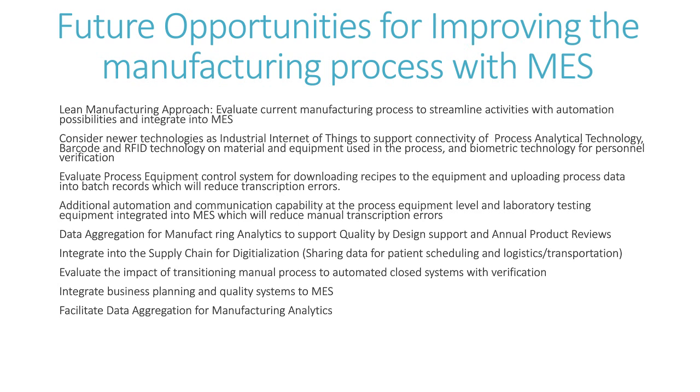You could look at the process equipment control systems and look at how we can download recipes to them from the MES, as well as upload process data from them into the batch records. Some of our clients are not there yet with their equipment vendors, but I would urge the equipment vendors to support that as opposed to an isolated data set. Many of them have printouts, but that's really not what you want, right? A printout in the clean room, you'd have to take it out, scan it, copy it, and put it into the system electronically as a PDF. Wouldn't it be much easier to have that already electronically communicated over the internet into your MES system?